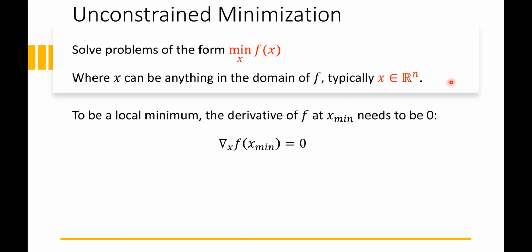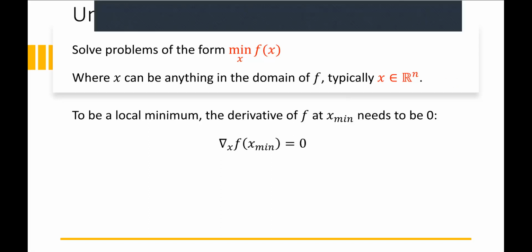So in this case, if x is a list of joint values, then I need the forward kinematics solution of that. And then as I change x, right, that's going to change where the Cartesian coordinates are, and I have an error signal there, from the desired XYZ position, let's say, of the hand. But there's not a straightforward relationship between those. So the robot doesn't actually have the answer in the coordinate system that it needs, right? The robot needs the answer in terms of joint angles.